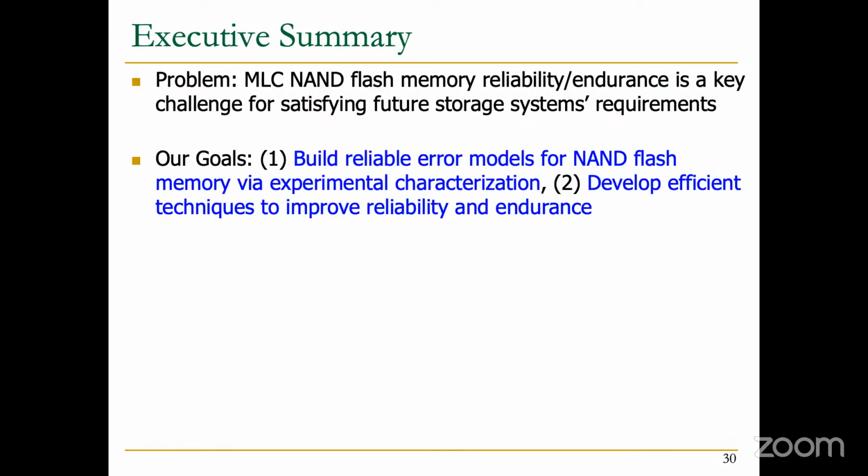What is endurance? Does any of you have an idea? Exactly. It is the number of writes, program and erase cycles, that you can perform. Endurance applies to flash chips and also to other emerging memory technologies that I guess Hayu was discussing yesterday. We have this limited number of program and erase cycles, so we call this endurance. Essentially, endurance affects the lifetime of your memory system.